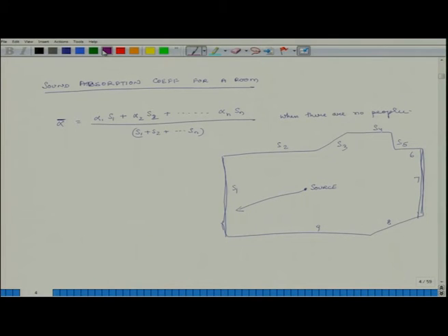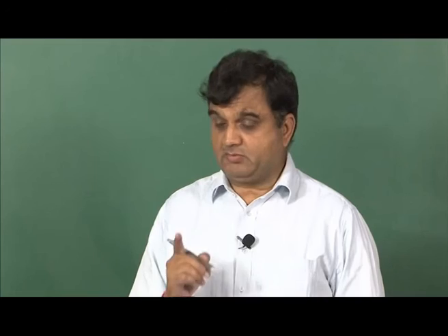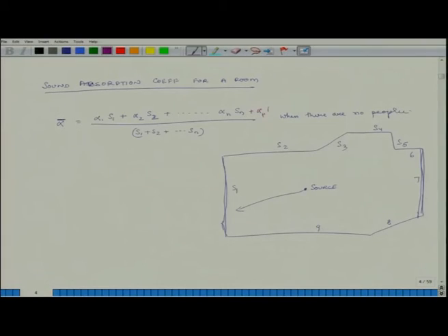So, we pick up those absorption coefficients for people, but suppose there are 100 people in the room. Then we add alpha p, p is for a person, and we do not multiply it by surface area of an individual, but rather we multiply it by the number of persons. Okay. So, if there are 100 people, this alpha p already accounts for some rough surface area of an individual. So, this is how we account for the presence of individuals.